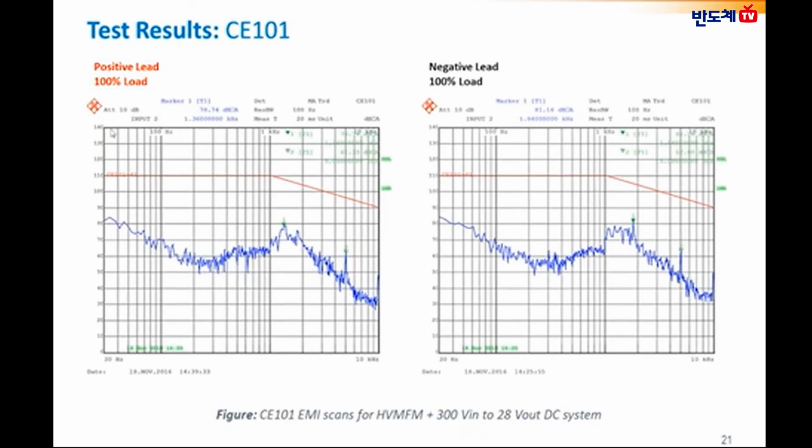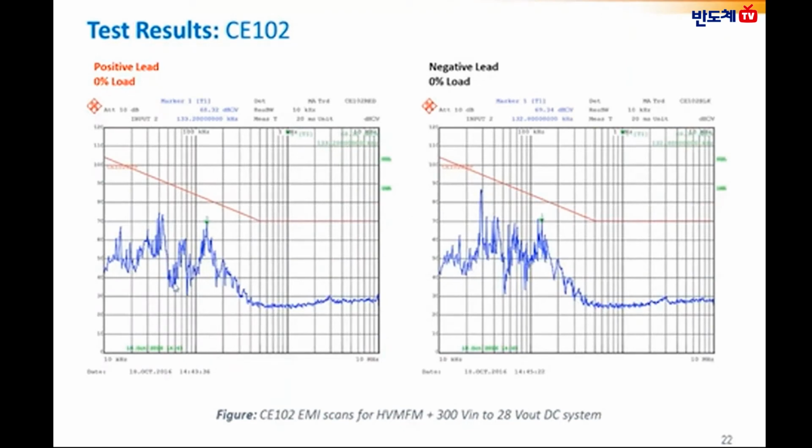The emissions in the low frequency show near to the limit line, whereas the overall test setup has base emissions, and on top of that the emissions of the EUT are plotted. Therefore, the emissions are very close to the limit line, but still within a 10 dB margin.